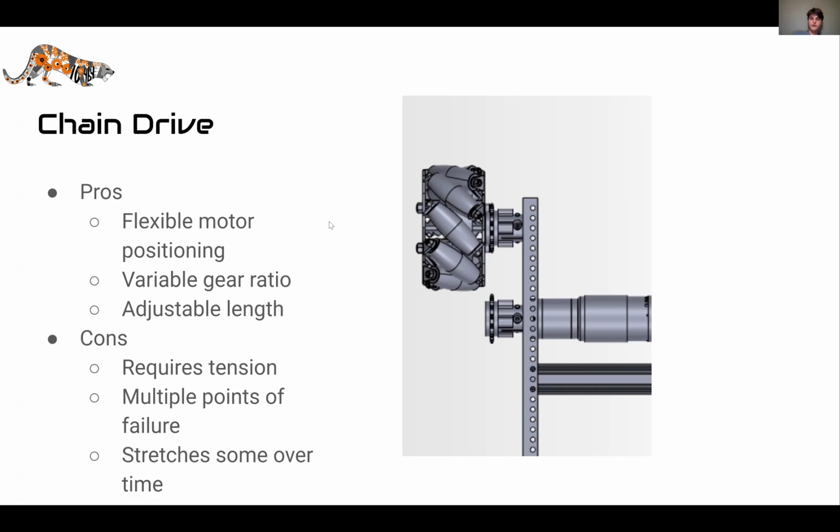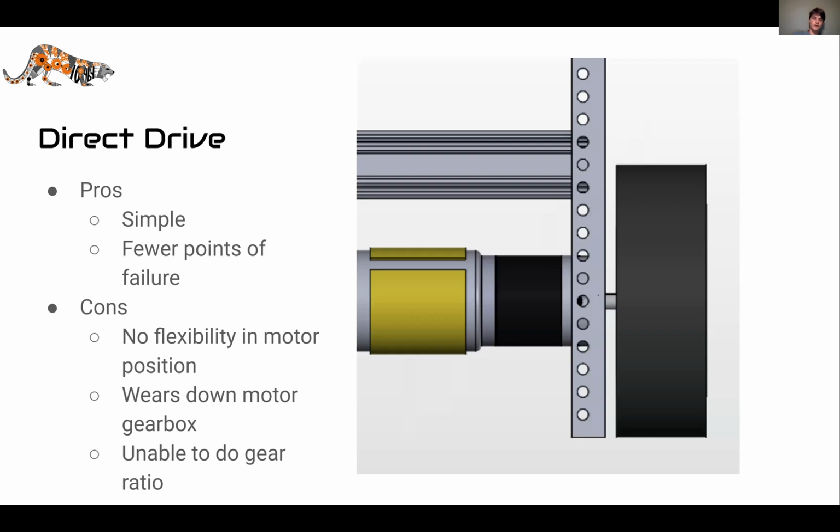And just something to note real fast about chains and chain stretch. Chain stretch is something that a lot of times in our past cases we've kind of discounted, but what happens is the individual links will wear a little bit, but over a long chain that compounds. So you just have to keep that in mind and make sure that you have a tensioning system that you can adjust to account for all of that.